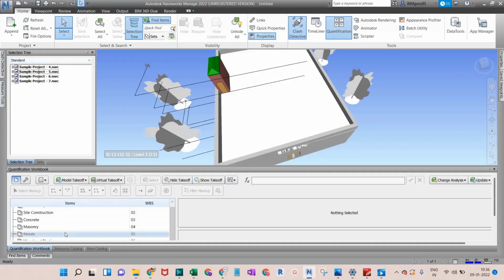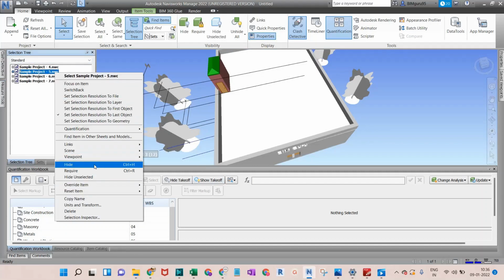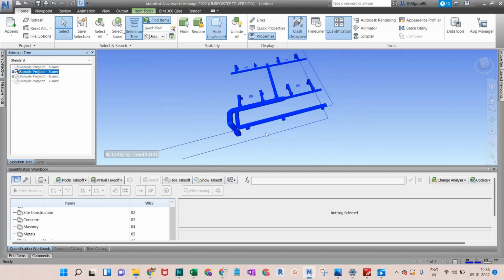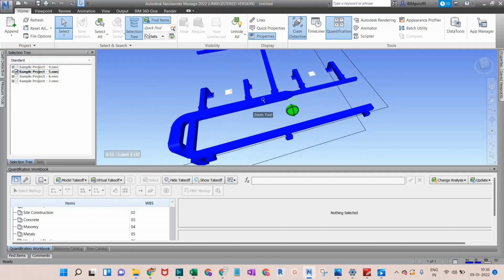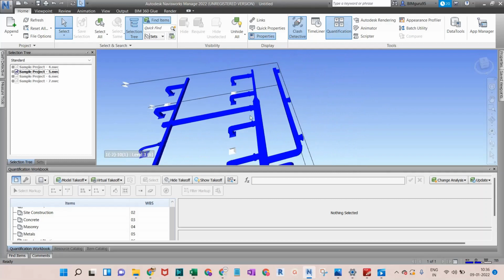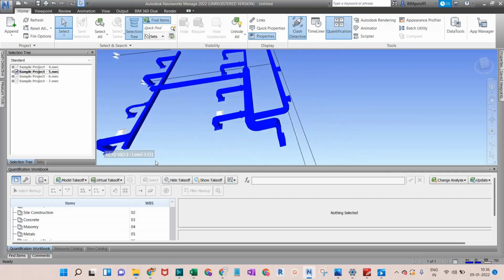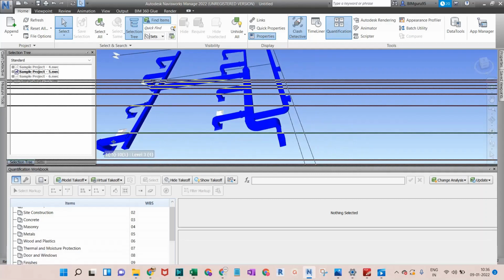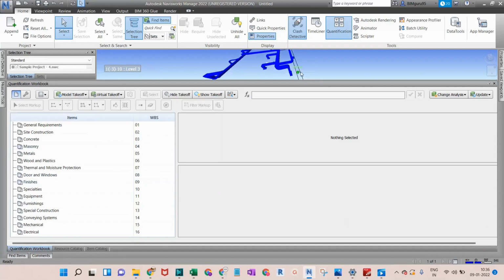So what I'll do, first of all, in that model as well, for which I wanted to create the takeoff. If I go to the right there, in this one we have ducts, duct fittings, air terminals, dampers. Dampers means duct accessories. Those kinds of things are right there, and duct insulation and something like that. Mechanical points are also right there. We have used that one.